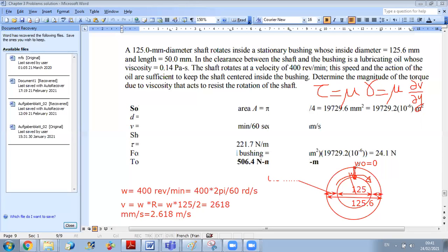Okay. So in order to calculate the shear rate, all I have to do is divide the linear velocity, because it's v minus 0, so delta v. Assuming you want a linear profile, whenever you have a very small clearance, you can assume a linear profile due to the small distance. Also, in case of a fluid with constant viscosity, the variation of velocity will be linear.